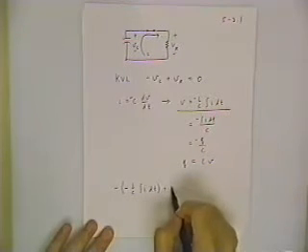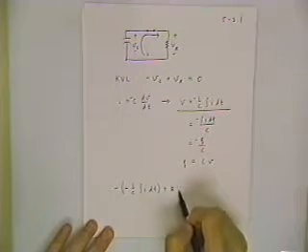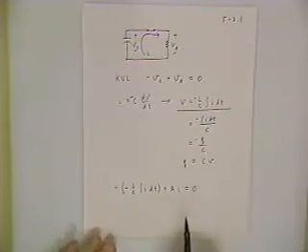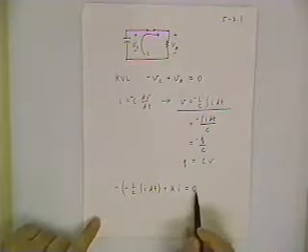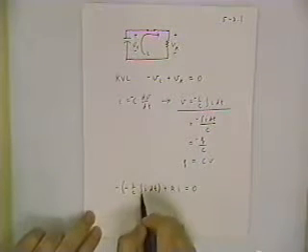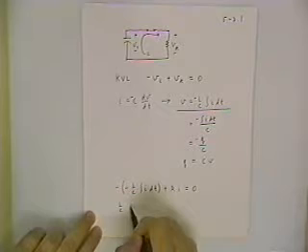For the resistor, it's much easier, just Ohm's law. V sub R is equal to R times I equals 0. And now if I differentiate this expression once with respect to time, it clears the integral.